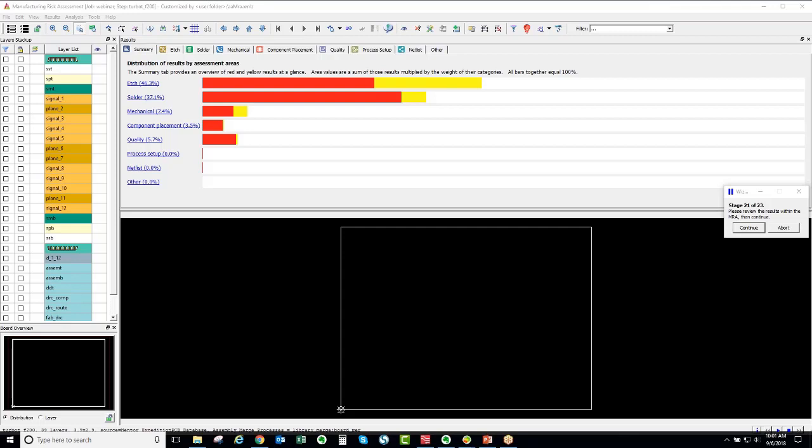You know, there's obviously other simulation tools out there to do that, where you can simulate shock and vibration prior to actually getting a board fabricated. But through the process of using a tool like that or having a consultant service figure out based on your solder joints and the materials you're using, you could determine optimal pin or pad geometry and then enter those as rules in Valor, so that every other design you check from that point forward, you would be able to have a good analysis of your design.